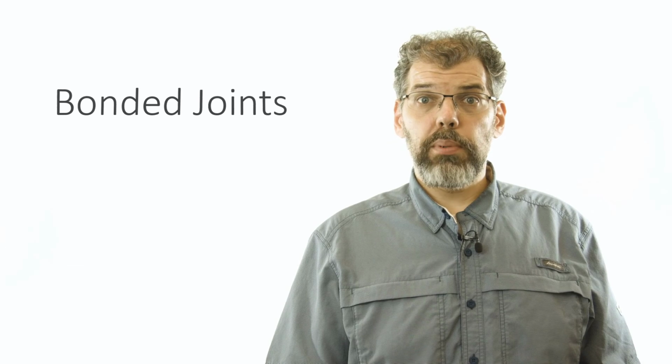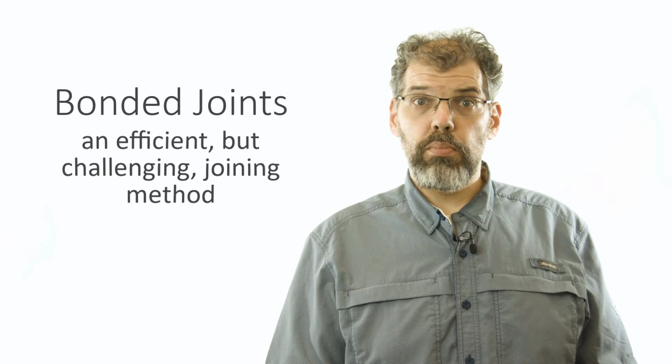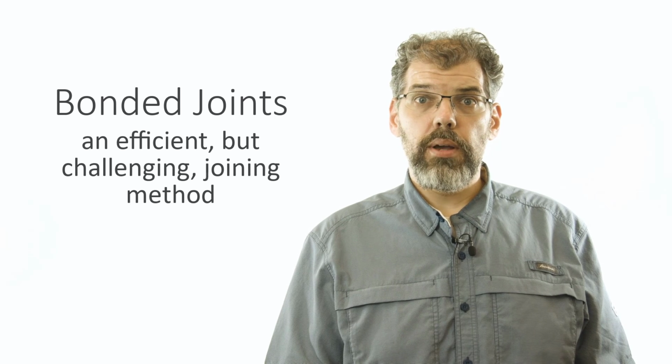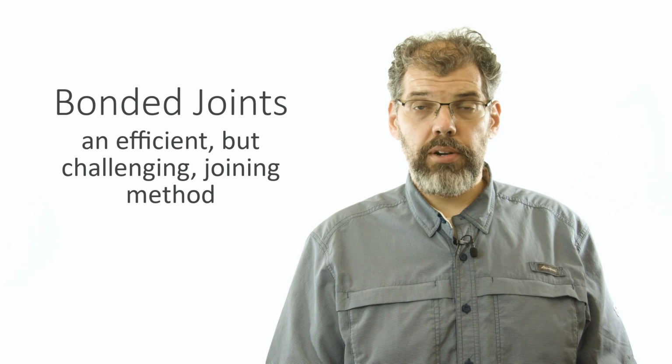So adhesive bonding is a chemical process that can result in a very efficient structural joint, but is susceptible to pretreatment and processing variations. Although as engineers we would like to exploit the efficiency of bonded joints much more, in practice, the challenges associated with process variations make it very difficult to make widespread use of the technology for primary structural joints.